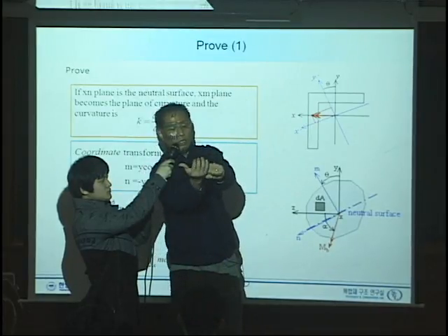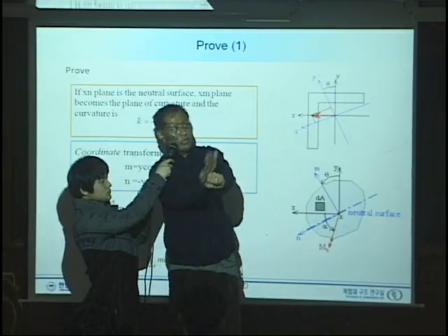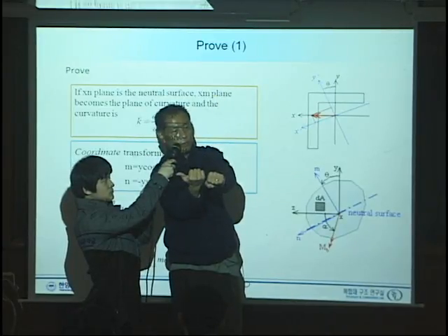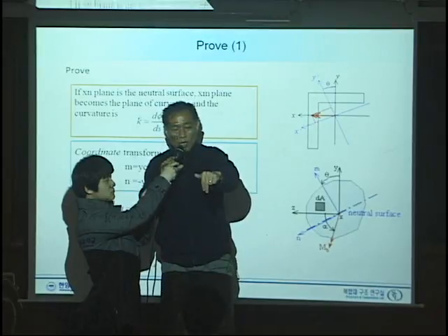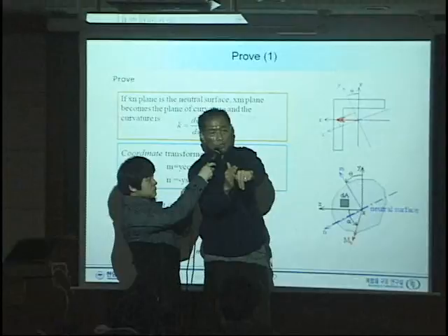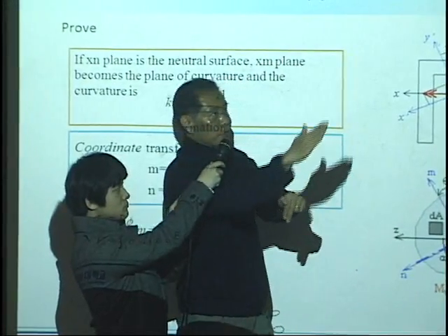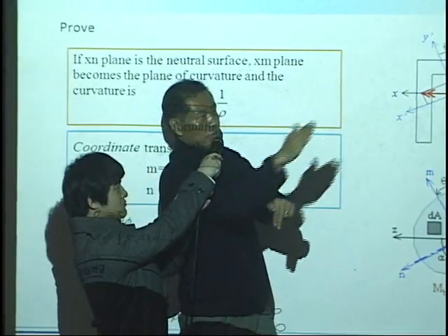So that way we define the bending moment, curvature. So bending moment and curvature are in the same plane. Now this one is unsymmetric. When we still apply the same moment, it is a totally different curvature. So this plane has been rotated.